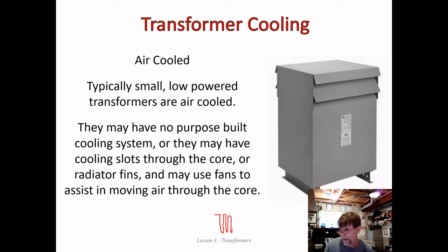So in the least amount of physical space possible, you provide the absolute maximum amount of surface area where that heat can be released into the air or dissipated. Okay, so that's what a radiator does for us. That's what the radiator fins accomplish: it allows that heat to get to a surface and then bleed off into the air.